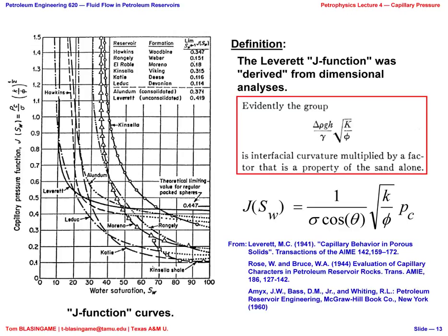Now, knowing what I just showed you a moment ago, what would you define as the characteristic pressure in this dimensionless capillary pressure? You'd use the displacement pressure, correct? The displacement pressure. The lowest pressure that represents the system. Why? Because it's convenient? Yep. No problem. All right. So you essentially anchor all the curves at one point, to the displacement pressure. But you also have to anchor all the curves to the irreducible saturation.